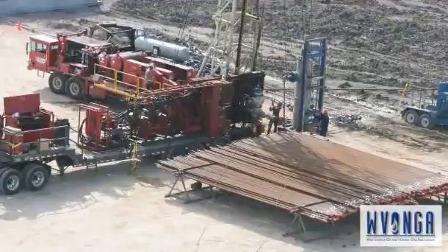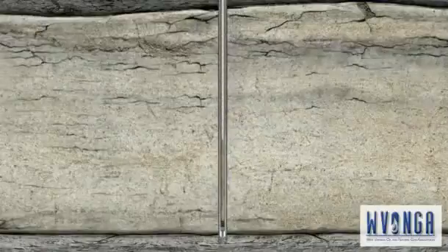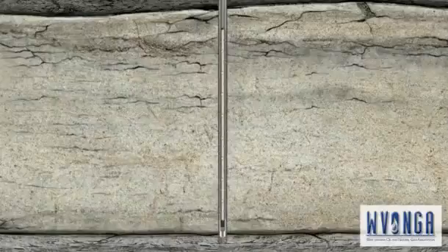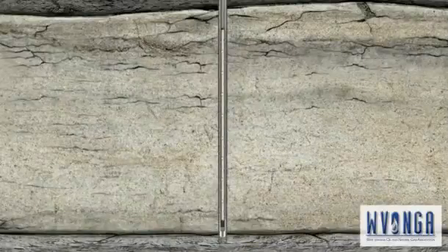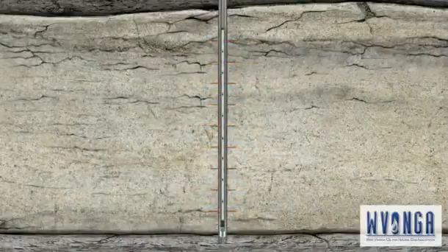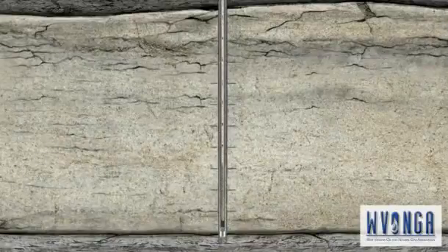The first of these steps is to perforate or perf the casing. A perforating gun is lowered by wire line to the lowest of the 3 target zones. An electrical current is sent down the wire line to the perf gun, setting off a charge which shoots holes through the steel casing, cement, and out a short distance into the target formation. The perf gun is then pulled out of the hole.